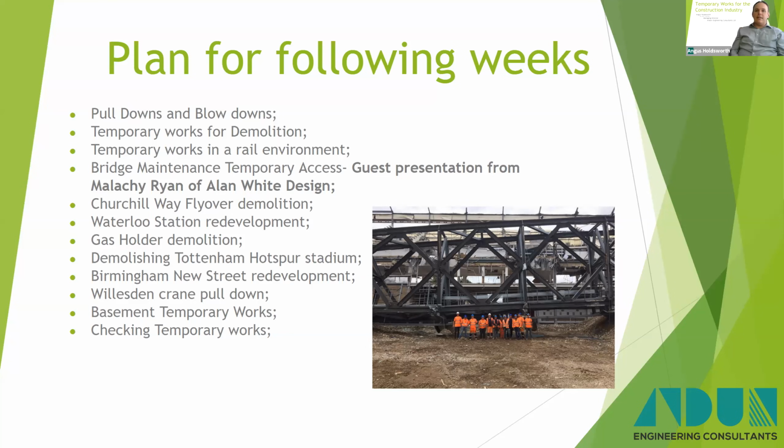And this comes back to that same question: is scaffold really an adequate system to prevent a building collapsing if something goes wrong when you're demolishing it? No, it's probably not. But there are things that can be done, and in a lot of cases, it's driven by the client request to have a scaffold around a structure that's demolished to help control dust and things like that. What has to be planned is how the demolition is going to be undertaken with the scaffold in place.